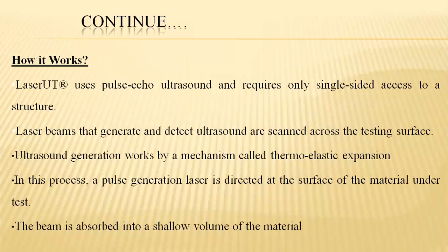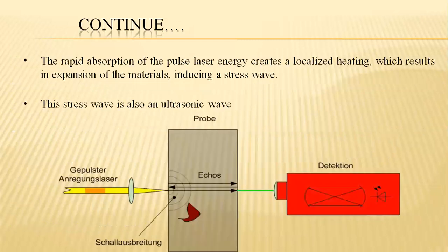The beam is absorbed into a shallow volume of the material, with rapid absorption of this pulsed laser energy that creates a temperature rise and results in expansion of the material. This is called the stress wave. That stress wave is the ultrasonic wave that is generated.